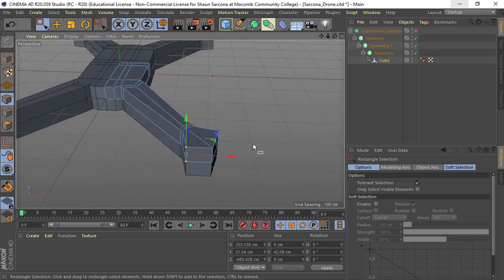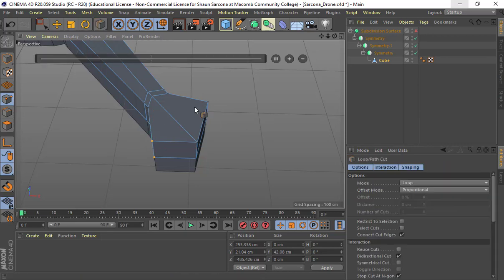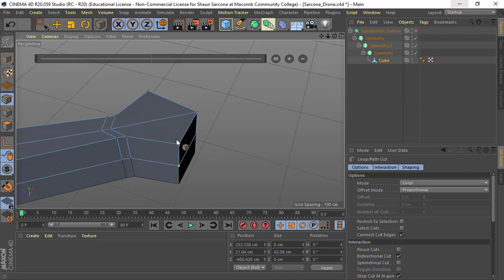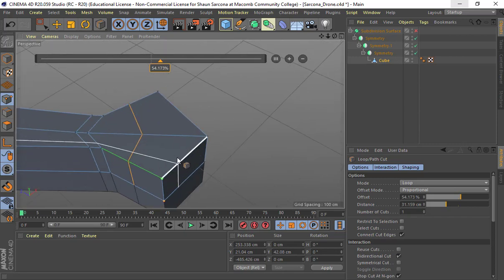All right, so now I need to add this area here. I want to get that to be a perfect circle where I could grab that and extrude it inward. Right now it's not set up for that, so I need to add more divisions. Now what I love to do is grab a division straight across here, which looks like I can do that, and straight across there. This one is not going to let me do that. You'll see as I drag this, it wants to go back to that other spot. Maybe I can do that, we'll see. I think that'll actually be fine.